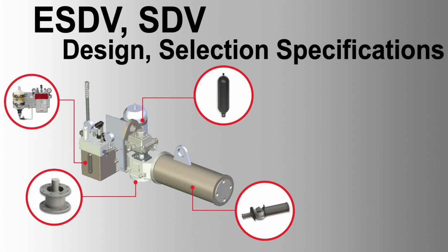Valve body general, flanged end connections, ASME B16.5. Face-to-face dimensions, ASME B16.10. Body construction, split type as per API 6D. Pressure ratings, must align with associated pipe rating. Fire testing certification, API 607. Anti-static and fire-safe design, all valves must be certified fire-tested per API 607 and be anti-static.